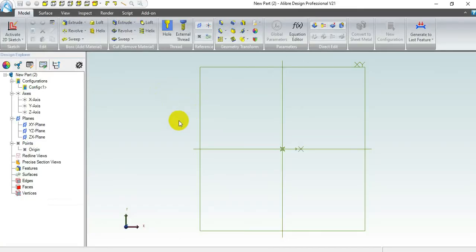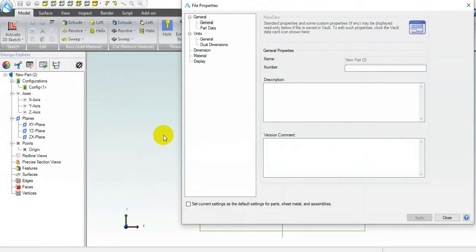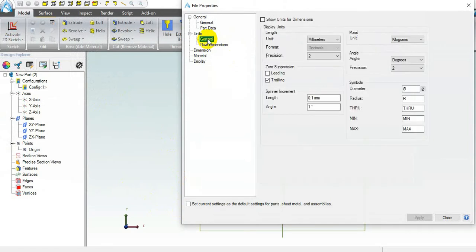And once this boots up, we just want to check a few things. Now we just want to make sure that we're in the correct options here. So we'll come down here on the top mouse button, top left corner. We want to go to Properties. Now all of these things here, I think we've just accepted the defaults on everything, so it's not been changed around much at all. But I want to just check out the units in the properties, and I think this defaults when it's first installed to inches because it's an American-based program.